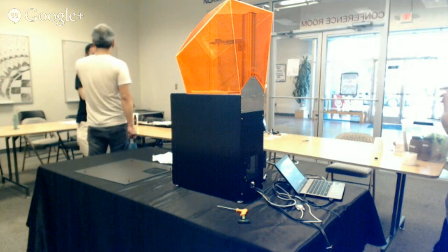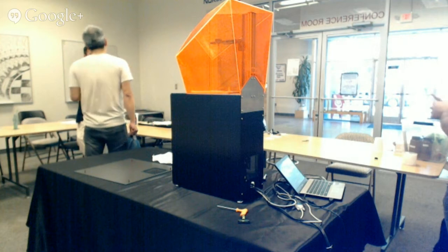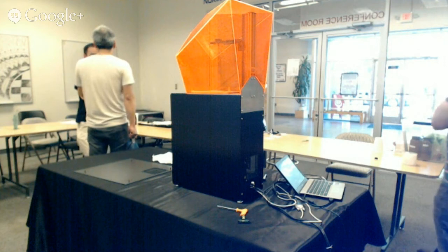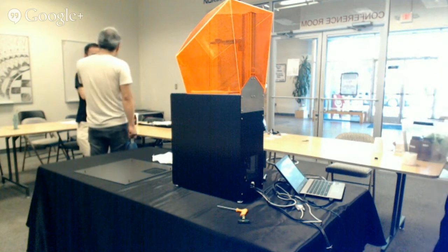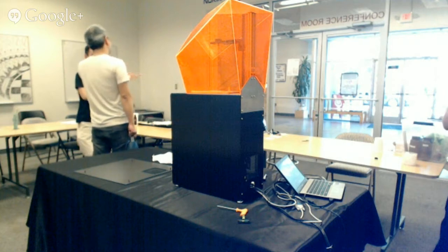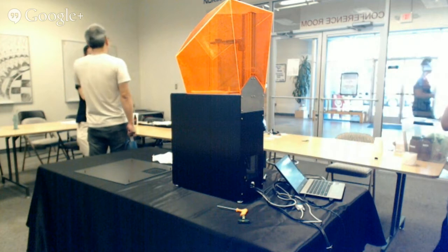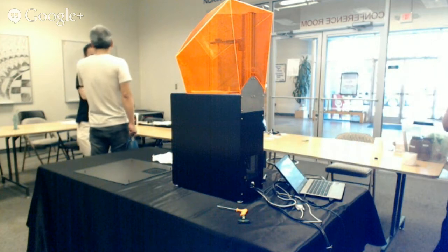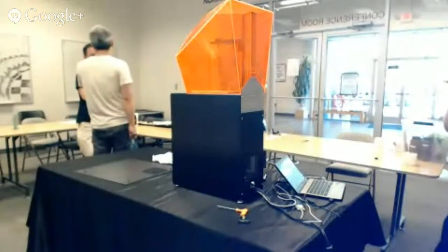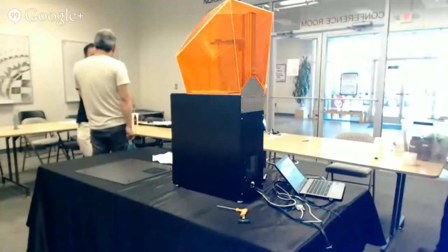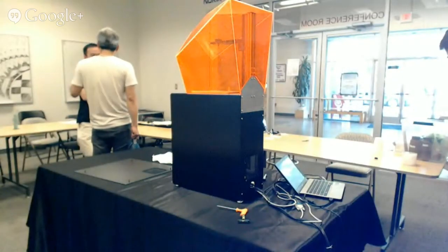It's not solid. Okay. So there's an aluminum insert that goes in here, held in position by this neck here, and it floats in the middle, and that produces a 1 millimeter thick piece. I didn't bring that part because I wasn't demoing, but yes, there's a couple of things. This hasn't been drilled all the way through because this part is scrap, so I have to drill this through, and then there'll be the aluminum. There's an aluminum insert that goes in this way, and then there's another bracket that holds the aluminum in, so when I inject, it doesn't blow the pin out.